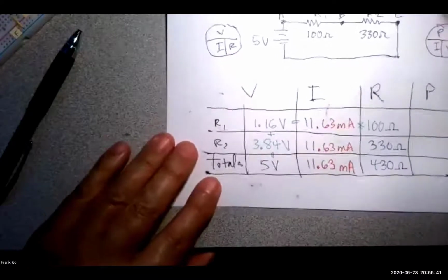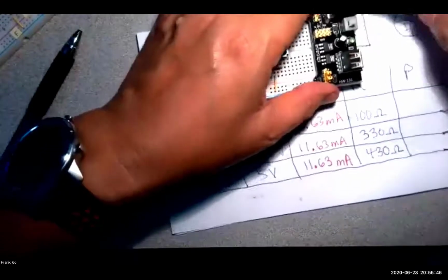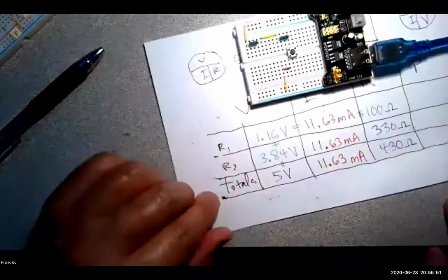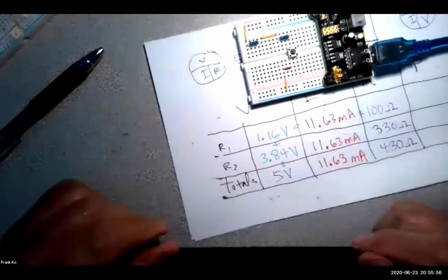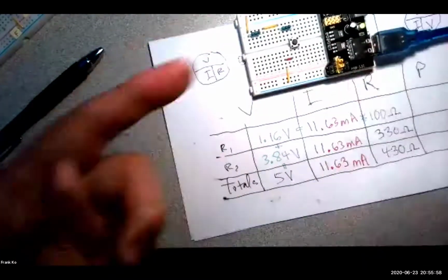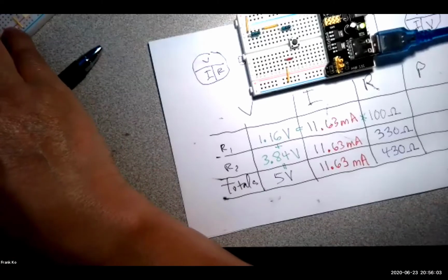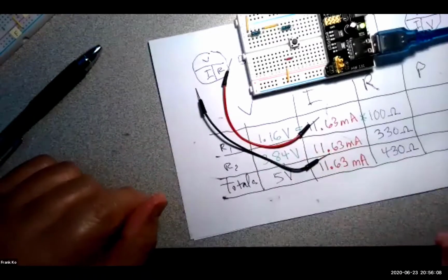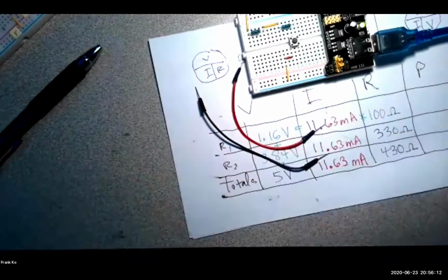All right. So I have the circuit built. Here's the circuit built. And I'm going to hook it up to power. So the circuit's hooked up to power. I'm going to energize my power supply. Power supply is energized. Now, the best way to make measurements, since these guys are cut down really, really low and it's hard for us to get in here, my recommendation is let's go ahead and use a pair of these pre-terminated pin jumpers. And we're going to use these in conjunction with your multimeter.